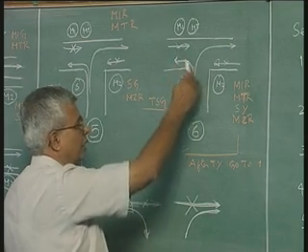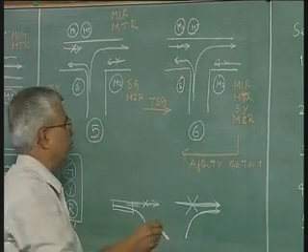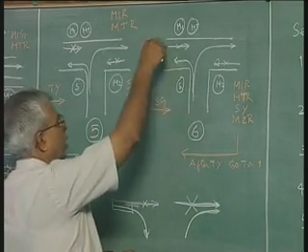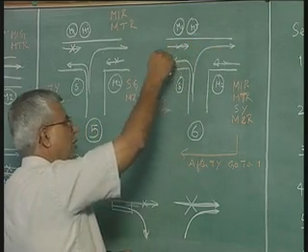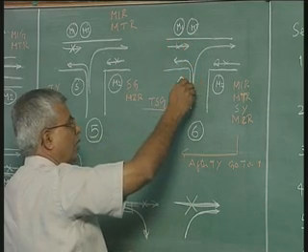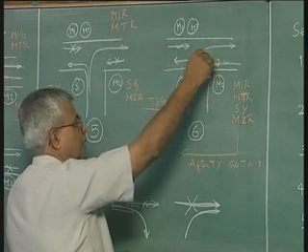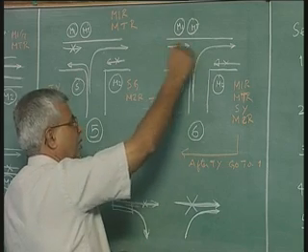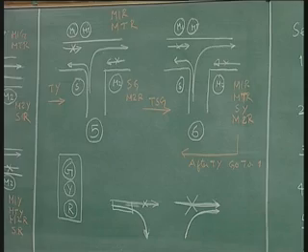So, after Ty, we go to S1. S1 is when left to right traffic is allowed on the main street and right to left traffic is allowed on the main street. No turning is allowed from main to side, no turning is allowed from side to main, but this free left and this left are allowed. That corresponds exactly to this state.